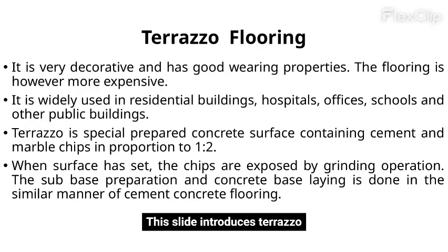This slide introduces terrazzo flooring. It's a decorative option with good wearing properties, making it suitable for residential buildings, hospitals, offices, and schools. Terrazzo is a special concrete surface containing cement and marble chips. The subbase preparation is similar to cement concrete flooring.